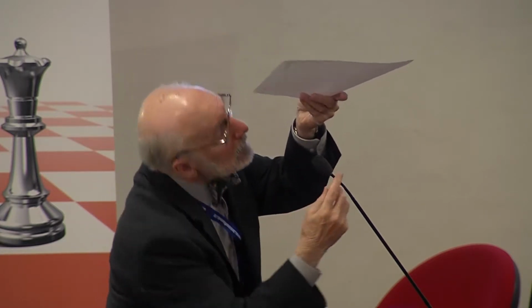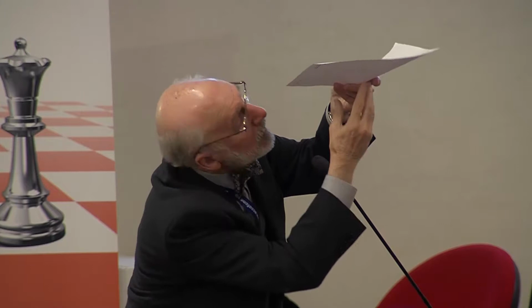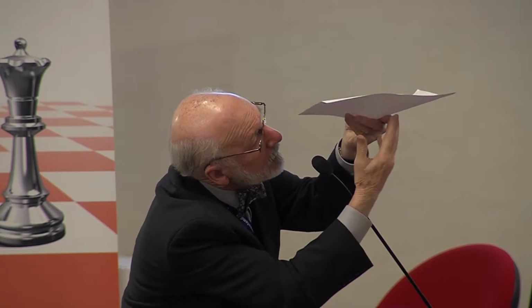but there's no problem with it being here while it stays on the top. But it has very special properties. The top is dry in contact with the air, and when you look at it under a microscope, it looks like sandpaper. Okay? But now, underneath, it's in perfect contact with the liquid because it's grown atom by atom from the liquid. So underneath, it's perfectly wetted, the top perfectly dry. Now, this has immensely important implications for our casting.